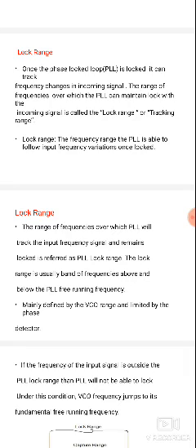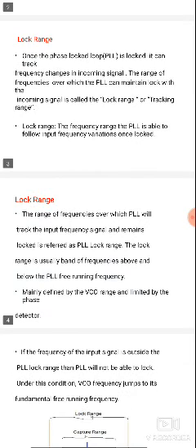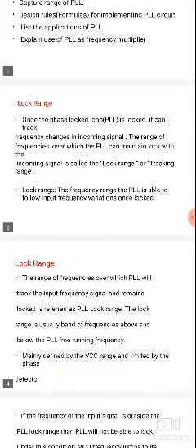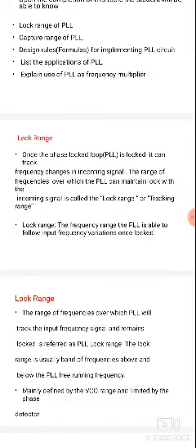If we are not applying any input, the circuit is in free running mode. If we are applying input, it is in capture range. The VCO output is checked and matched with the input of the phase detector or phase comparator. These we already completed in previous sessions.